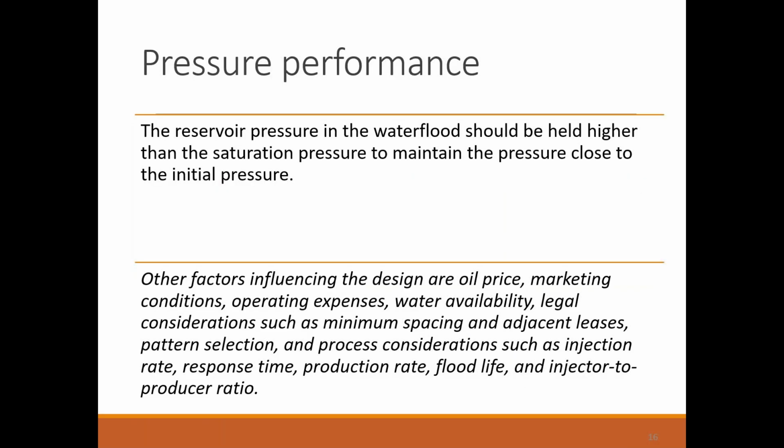Now coming to the pressure performance. The reservoir pressure in the waterflood should be held higher than the saturation pressure, to maintain the pressure close to the initial pressure. I have dealt in detail on the very first slide, where I said that reservoir pressure should be greater than saturation pressure as well as the hydrostatic pressure, and now I am telling that this pressure should be close to the initial pressure.